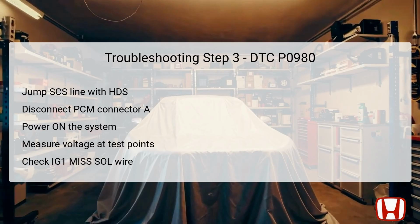In the third troubleshooting step, commence by jumping the SCS line using the HDS to initiate diagnostic mode. This step ensures that the system is fully prepared for subsequent checks. Next, disconnect the PCM connector A, which is crucial in the communication between various vehicle systems. Once disconnected, press the engine start-stop button to switch to the on mode, thus providing power to the system while isolating the PCM.